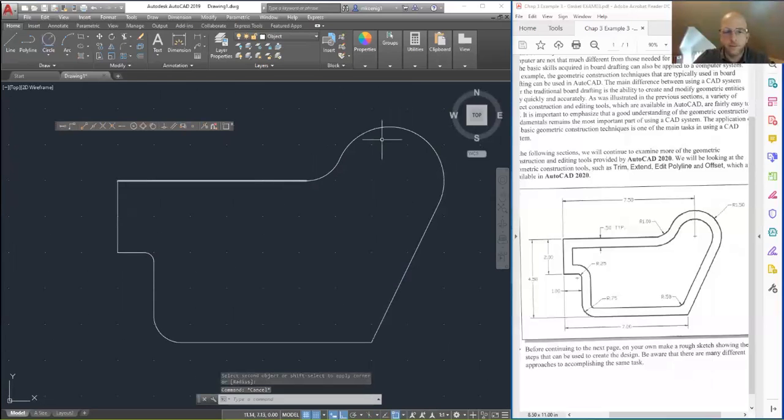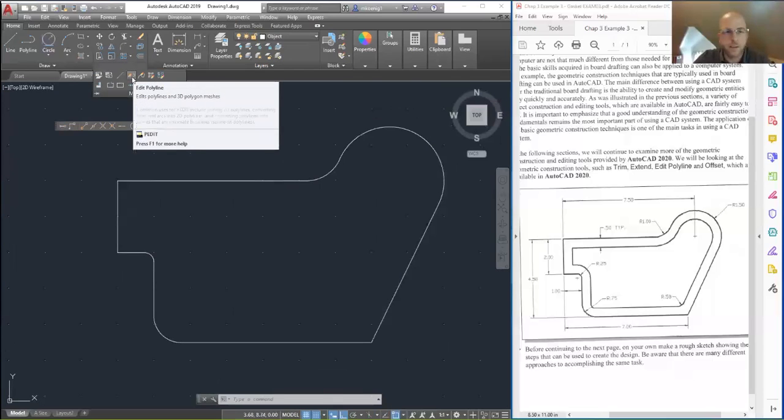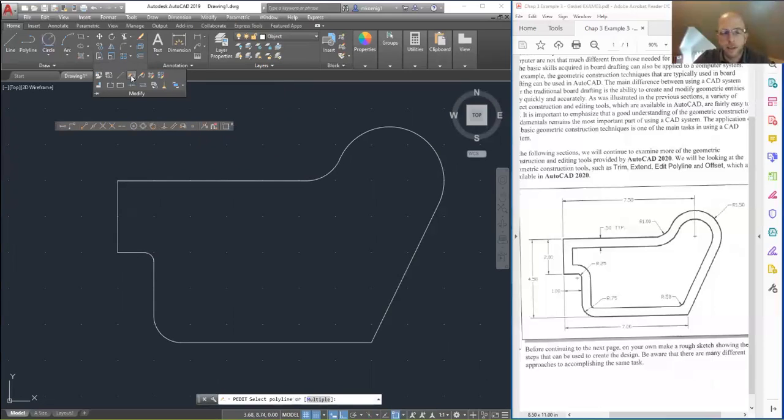Now what we can do is see how these are all separate lines. To make things a little easier for us, we can convert this into one polyline object. Modify menu. There's a command called edit polyline. Looks like a pencil and a line. If I click that, you'll notice on the command line, the actual type-in value would be p-edit if you prefer typing.